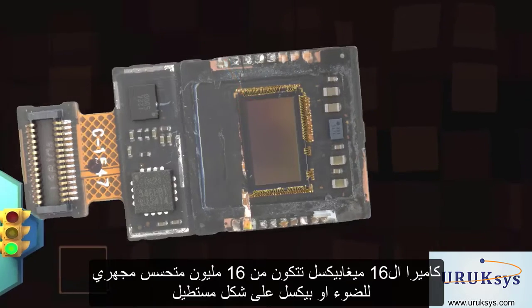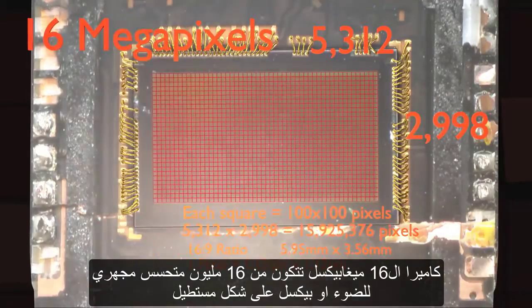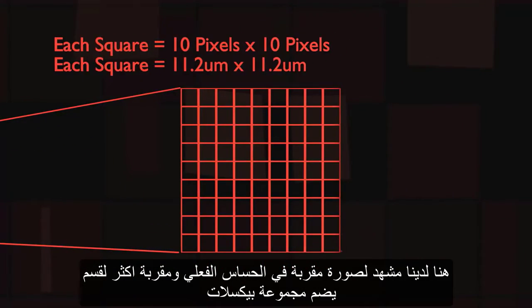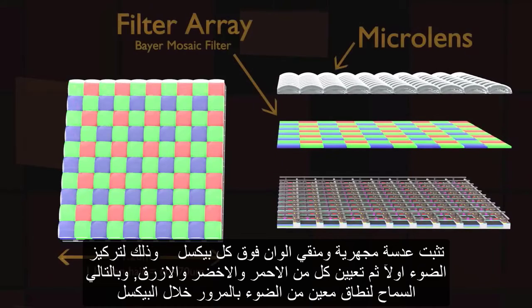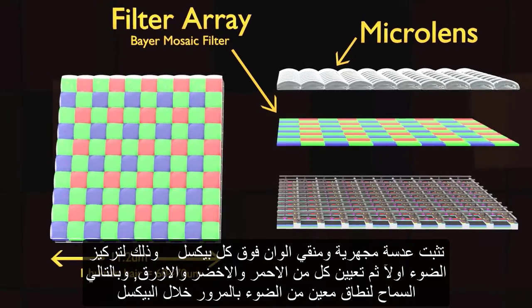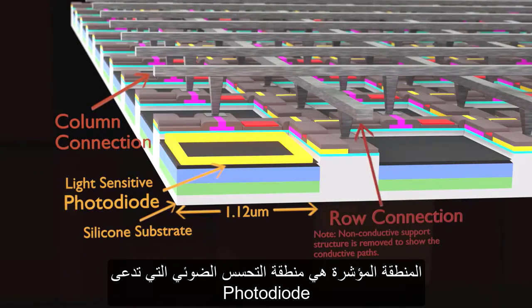A 16-megapixel camera has about 16 million of these tiny light-sensitive squares or pixels in a rectangular grid. Here we have a zoomed-in image of an actual sensor, as well as an even more zoomed-in cross-section of a pixel. A microlens and color filter are placed on top of each individual pixel to first focus the light, and then to designate each one as red, green, or blue, thereby allowing only that specific range of colored light to pass through and trigger the pixel. The highlighted zone is the actual light-sensitive region called the photodiode.